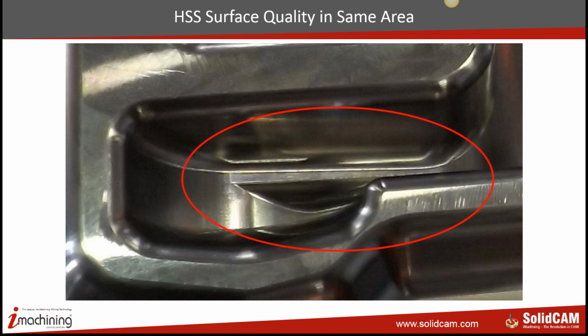It's a very old school of thought, because in the earlier days, in the late 80s and early 90s, when CAM was still evolving, there were systems like Computervision, SmartCAM, etc., and they had this principle of machining surface by surface. The finishing used to be done on one portion of the surface, then another portion, and so on. A similar principle was used here to machine this using HSS. Everything, including fillets, the floor, and the wall, was machined separately.